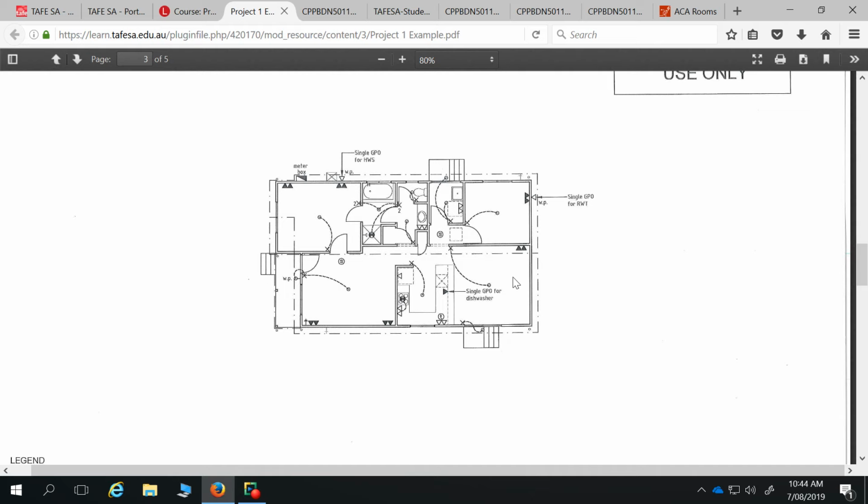Like if they've got an island bench with a good PowerPoint on it. Yeah, that's right. Most island benches they'd want some power. If it's completely disconnected, as an island would be, it can't come from the ceiling. There's no wall there. So they need to make sure there's an allowance for that pretty early in the slab. And so yeah, if your microwave's in that island underneath and a dishwasher, as I said, there's two points of power. And those switches aren't really accessible for daily use.